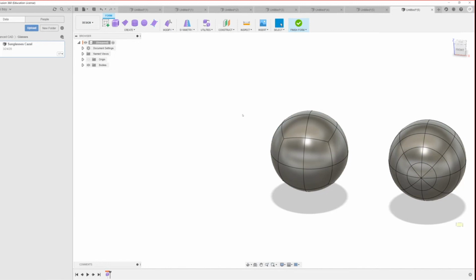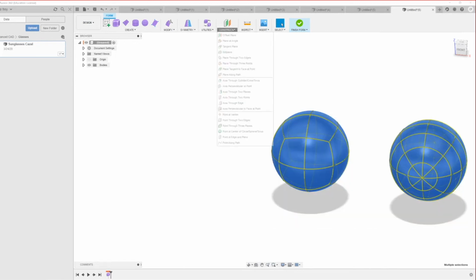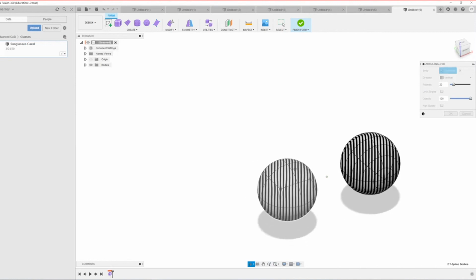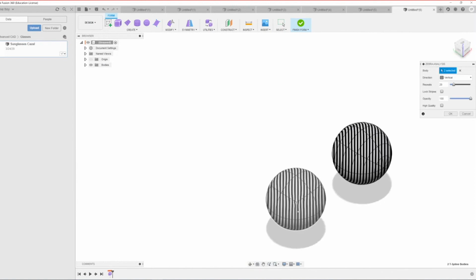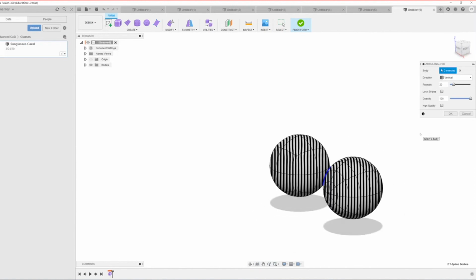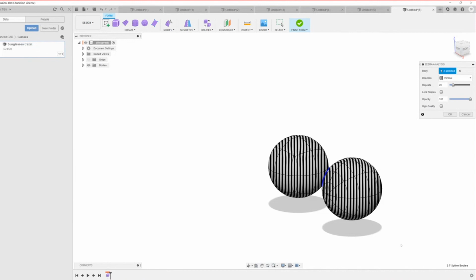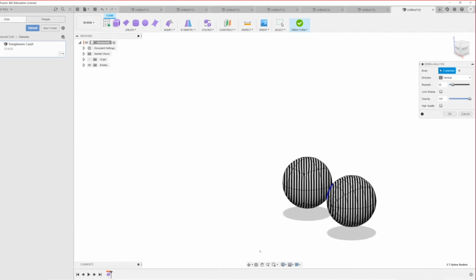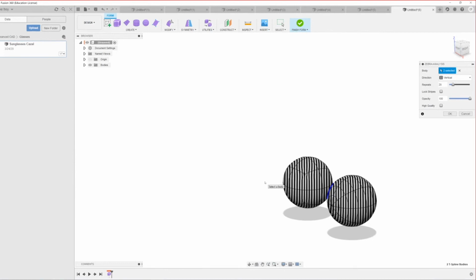But even if we go into our zebra stripes, we can see here that the quad ball has a little bit more deflection around the edges. But you're highly unlikely to notice that, because you don't normally end up with just a ball, a complete sphere shape. If you wanted to use just a normal sphere shape, I would probably suggest just modeling it up in a solid state.